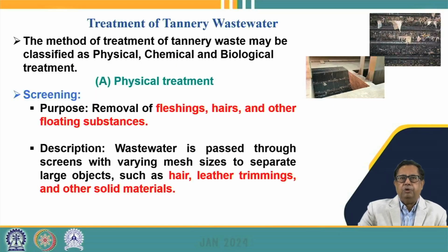So now let us talk about the treatment of tannery wastewater. We can have different methods by which we can treat it: physical methods, chemical methods, and biological treatment methods. For example, in the physical treatment method, screening is required first of all, so that we can remove the bigger particles as well as some finer particles.